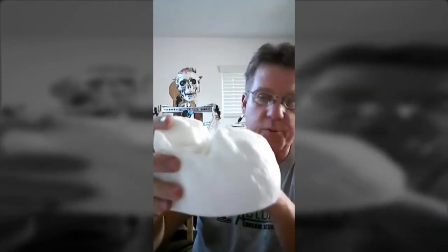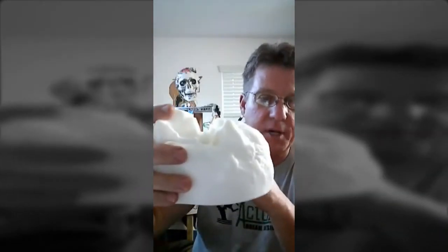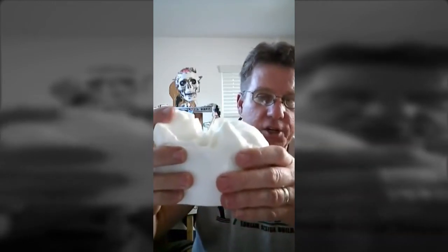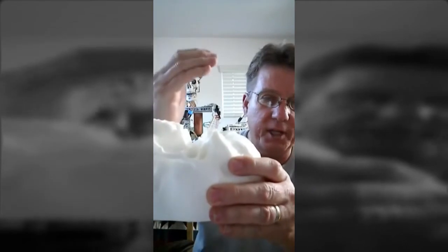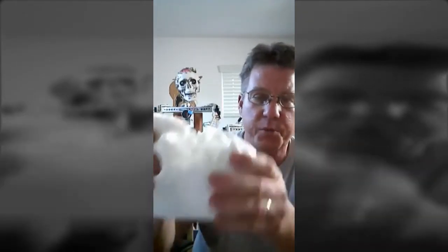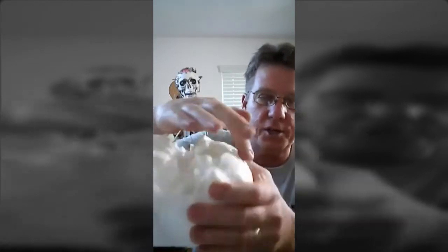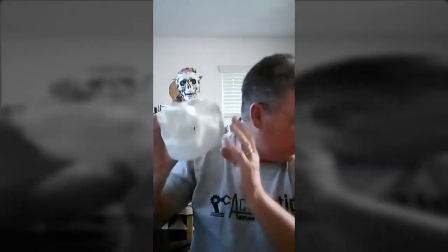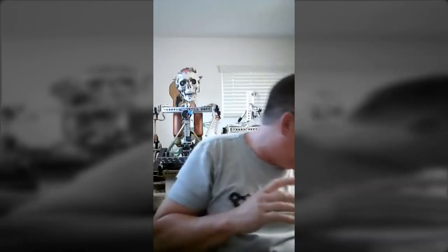So my preferred way now is to set this on the plate of my drill press, have somebody help so that we can get a nice secure grip on it and just be real easy, come out and clear the debris out of this hole as you're cutting it, because that can be a real pain. It can be a knuckle or wrist breaker when you're trying to drill this bigger hole in the bottom. So that's one thing that I don't think I've ever seen anybody mention before, but it can be a real issue that I wanted to mention.